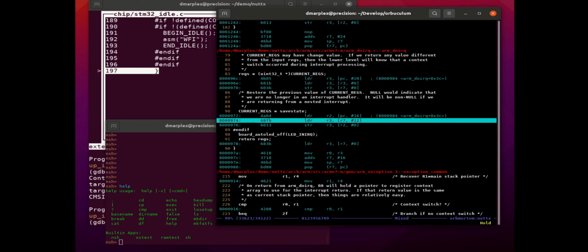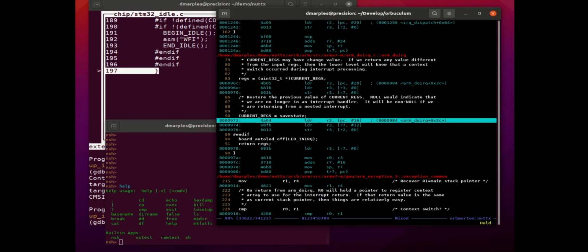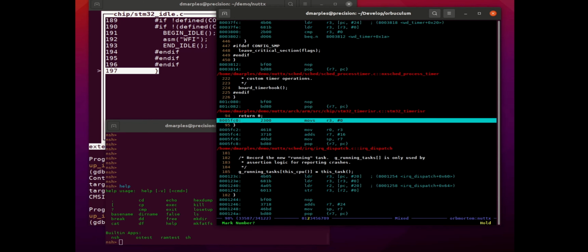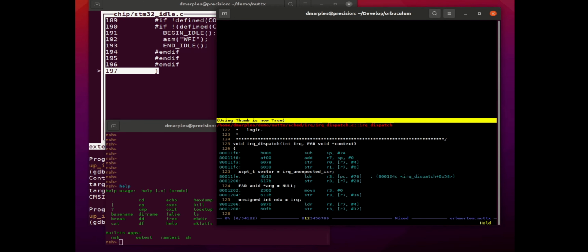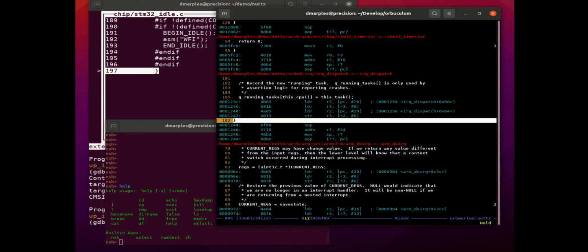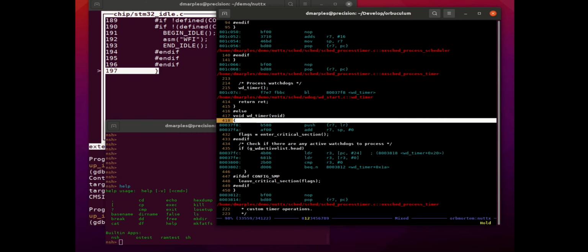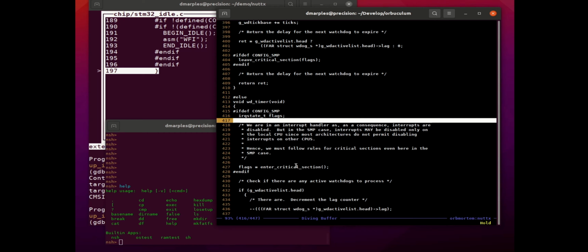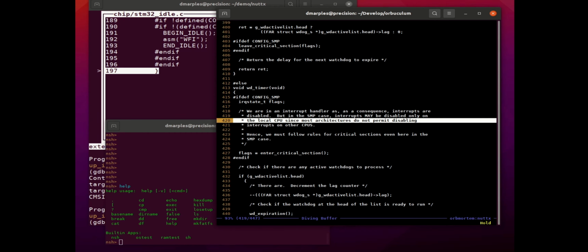What gets more interesting is when you want to look around inside the code. So for example, you can put markers on it. So I'll put a marker for 0.2 there, I'll put a marker for 0.1 here. I can move it to the beginning of the buffer and go to 0.1, go to 0.2, change modes. And then we can also do things like, for example, there's an interesting one, there's a watchdog timer. So we'd like to dive into that and say, in the source code, what does that correspond to? Because although that line is executing, I can't see it in the context of the program. So we just hit the right arrow key, and it will take us directly into that piece of code, which it pulls from the disk and delivers it to you, so you can see what's going on.